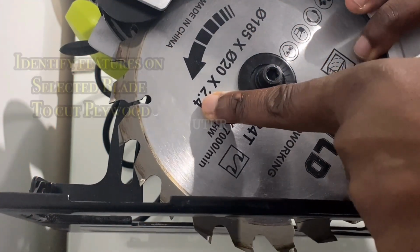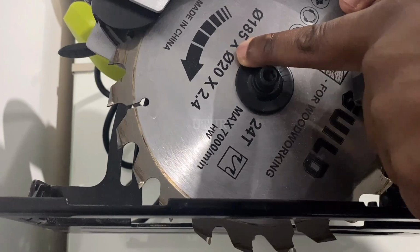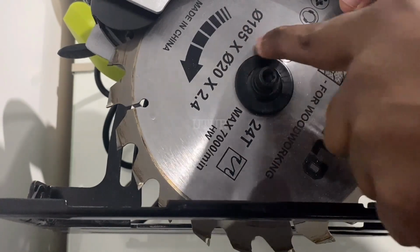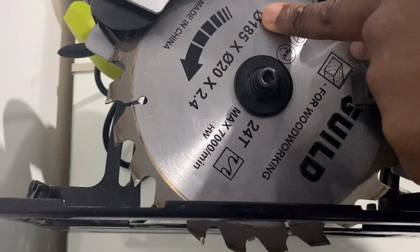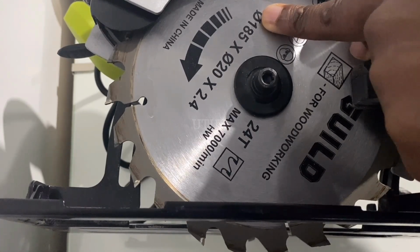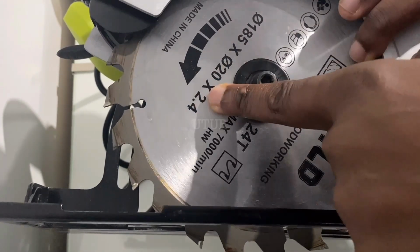And so now back to the blade in our Guild working tool. It's got a 2.4 kerf, a 20mm center bore and a 185mm rim size. And so this is the center bore. You want to do it with an Allen key if you want to change the blade. Okay, so again, that's your rim size at 185, your center bore is at 20mm and your kerf is at 2.4.